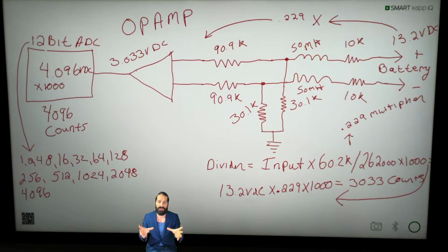Now, it's very important to understand what this is doing and why it's doing it, because when we're troubleshooting monitoring circuits, if you don't understand the very basic premise of input divider circuitry and how each system is either limited or enhanced by its inherent design characteristics, you can miss quite a few things. I'll give you an example. Let's say we go to a facility that has 242-volt wet cell batteries, and these 10K current limiting resistors are sitting on top of the battery system.